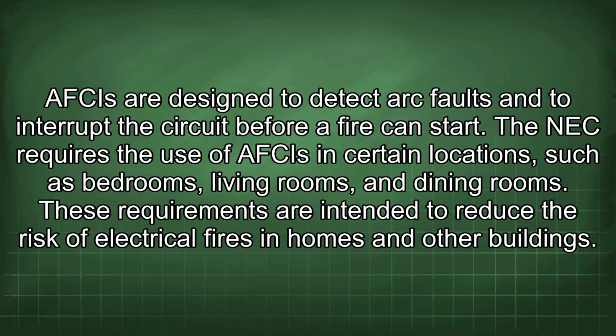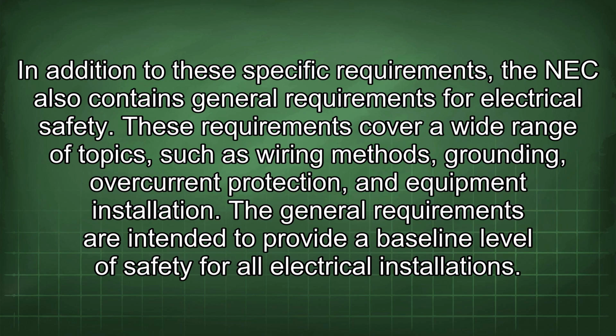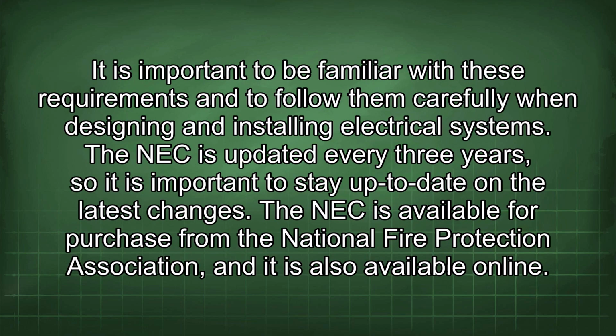The NEC requires the use of AFCIs in certain locations, such as bedrooms, living rooms, and dining rooms. These requirements are intended to reduce the risk of electrical fires in homes and other buildings. In addition to these specific requirements, the NEC also contains general requirements for electrical safety. These requirements cover a wide range of topics such as wiring methods, grounding, overcurrent protection, and equipment installation. The general requirements are intended to provide a baseline level of safety for all electrical installations. It is important to be familiar with these requirements and to follow them carefully when designing and installing electrical systems.